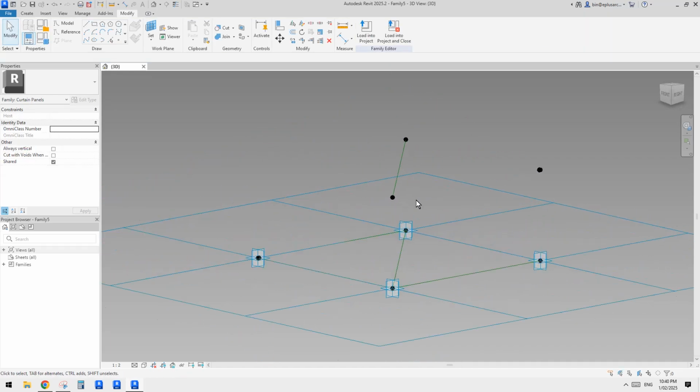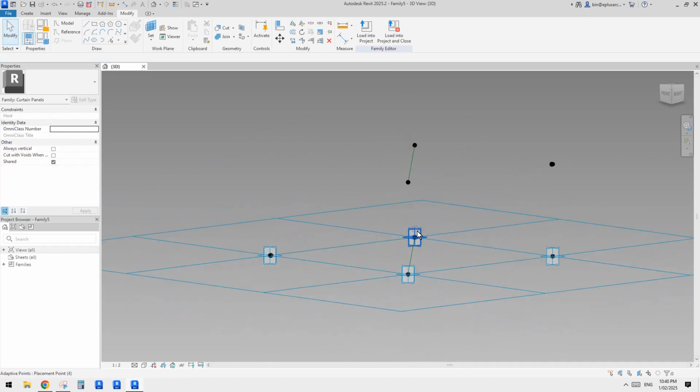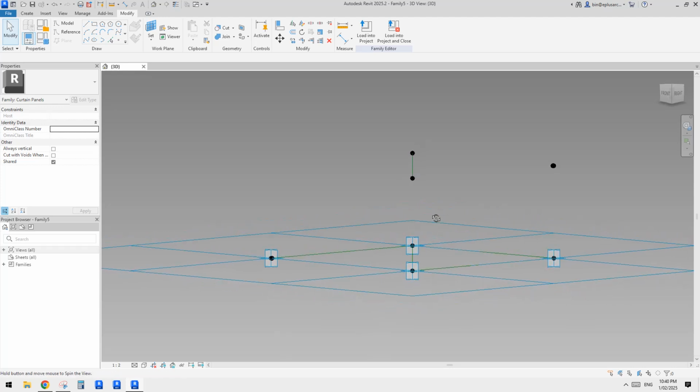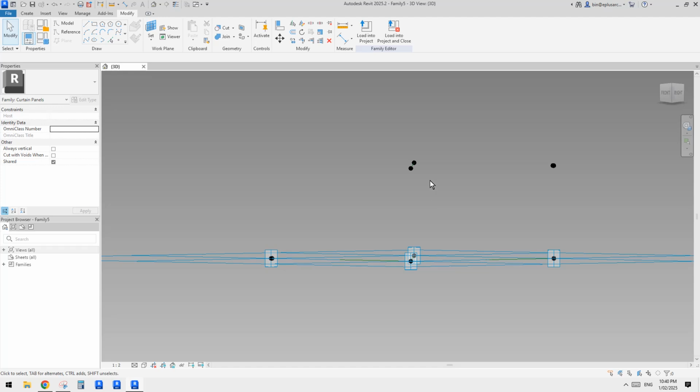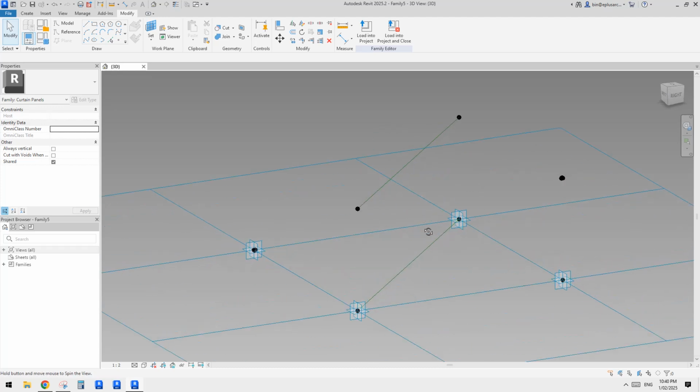So what we want to do here is we try to make it easier for Revit to understand. So you can see if I rotate this, we try to move this line just temporarily or change the shape so the line is more like sitting here, and then this one is more like sitting here. So when we try to use this full profile to create the shape, Revit understands what we want to achieve. Okay, so now let's do that.